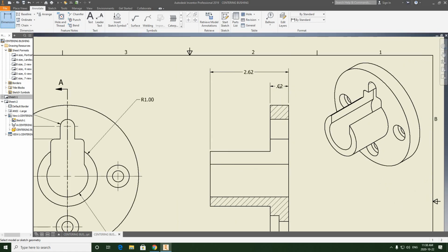We don't include a full chain of dimensions as well as an overall dimension. That's over dimensioning. We always leave one dimension out in a chain. So there's only two to show here possibly. So we show this one, don't show this one, and we just have the overall. And this is in the basic dimensioning rules note that's attached to the basic solid modeling module that you've seen.